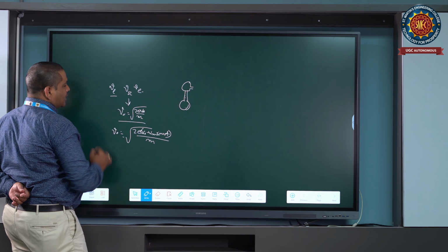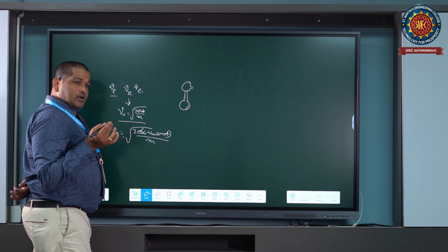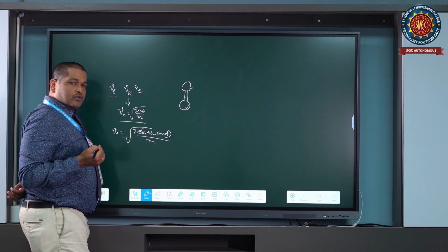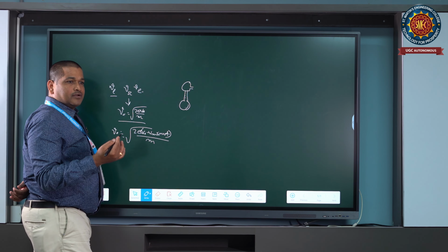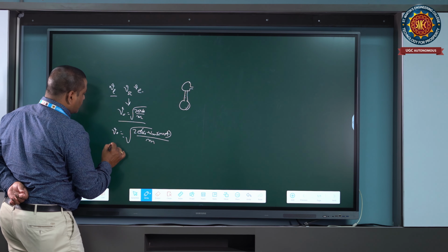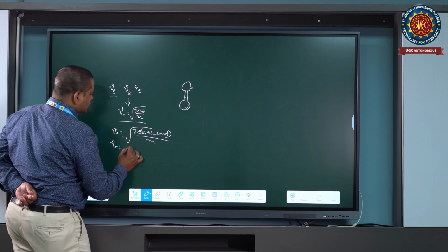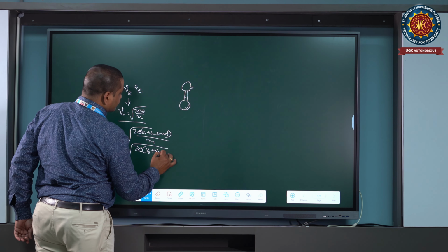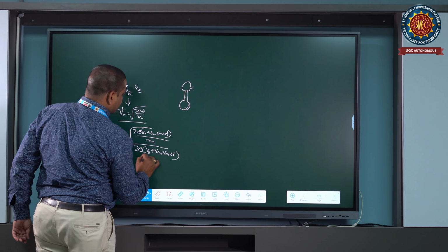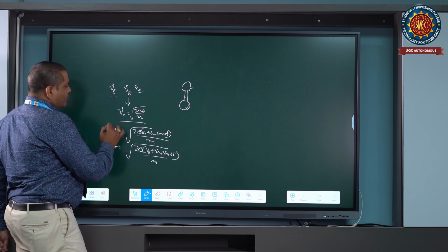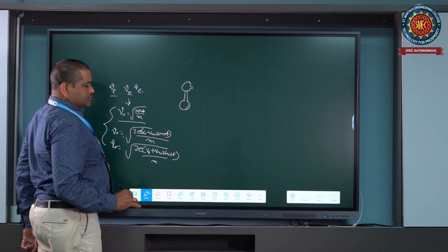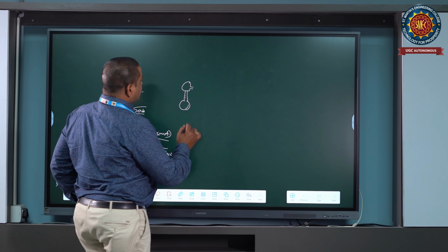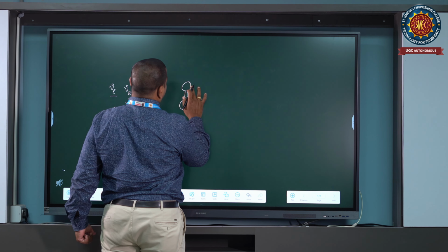And there is a late electron that is moving later than this reference electron, which has the low velocity. It should be accelerated. So for that electron, we will give the velocity which is equal to root over 2e (V0 plus Vm sin omega t) by m. This type of velocity modulation will be used in the two cavity klystron, where the electron, once it enters into this buncher cavity,